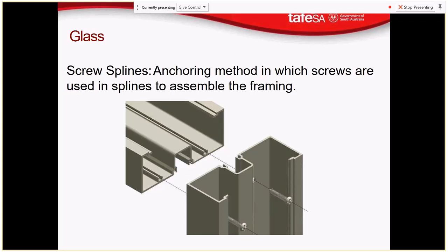And our piece of glass fits in here. When the piece of glass fits in there, it squashes that point down to keep that under pressure all the time. So for the rest of its life, it's being bent back and it's pushing against the glass, creating that seal. So if you wanted to have a look, yeah. These ones have got mastic in there, but that's what those channels are for, for accommodating rubber.